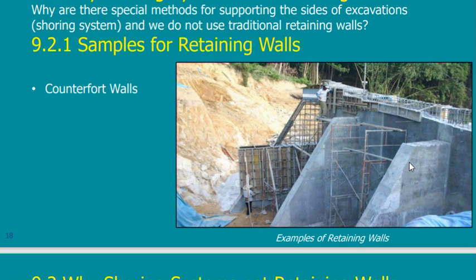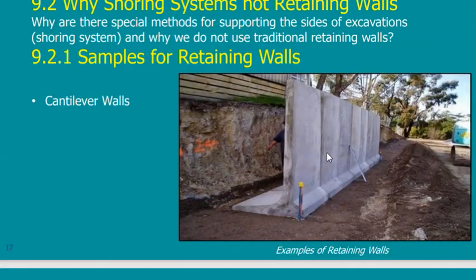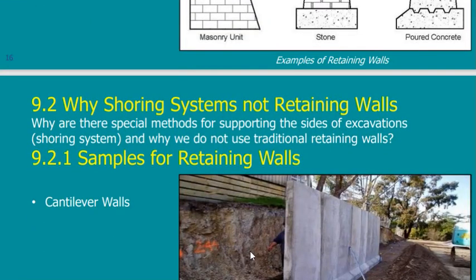So I don't need any prior excavation. But to construct this or this or this, you can see here in the photo, this is the soil. They needed to remove the soil first and then construct these walls, and then after constructing the wall, you see here the hand of a person. So after finishing, they are going to backfill here, and that's all. So they needed to conduct a prior excavation.